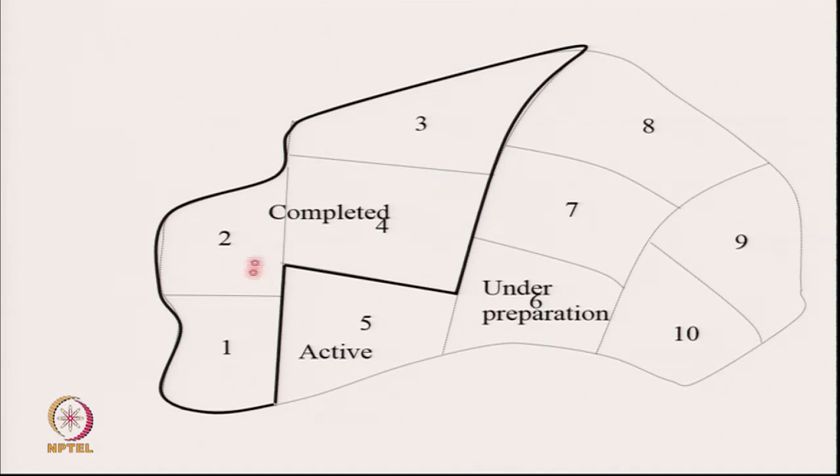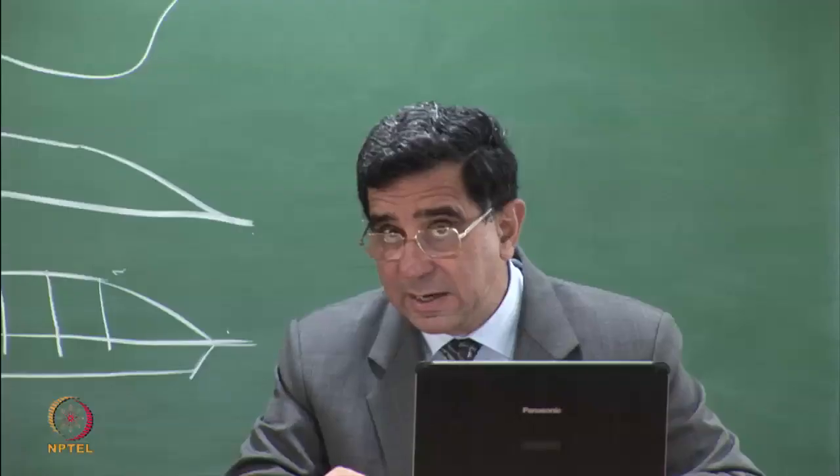I have to manage the leachate which is coming out of 1, 2, 3, 4. It will have its own wells. I have to manage the surface water which falls on this. That means it has to run off into some drains. So there has to be a surface water drain. If all this water falls into the active phase, it will make more leachate. We don't want it to make that.